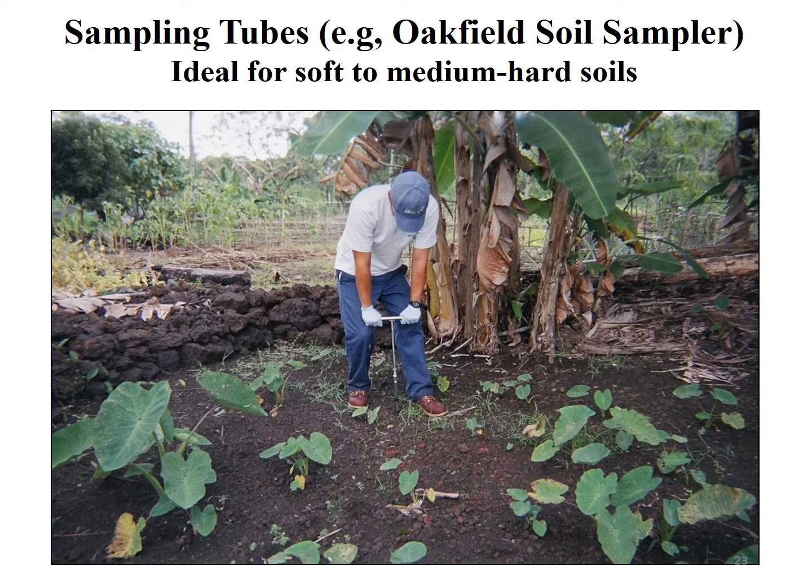A simple agricultural T-handle coring device, which has one side open that you can use to put a tool like a screwdriver in and pull out the core. Works great in soft soils. It's really fast. You can grab your increment, put it in your sample container, punch out the increment collected through the open side of the core, and move on.